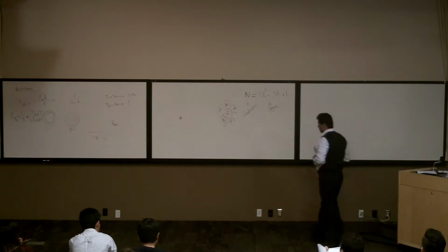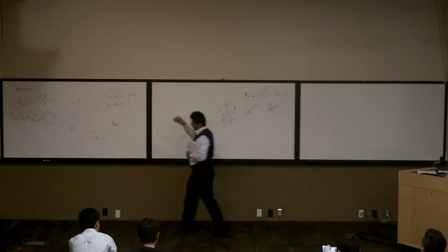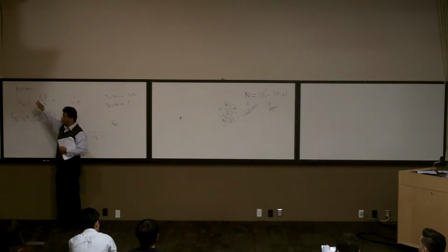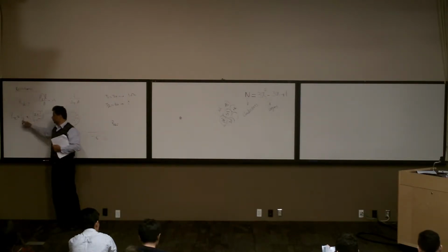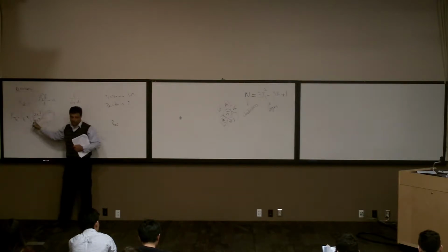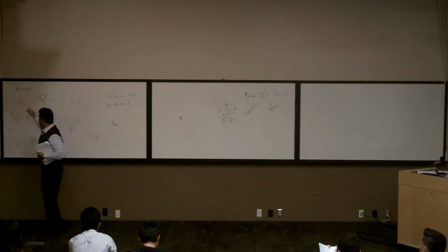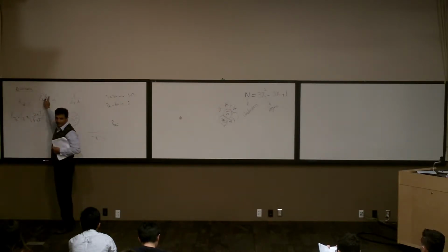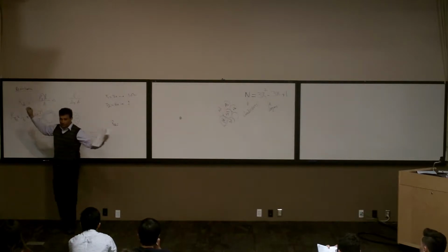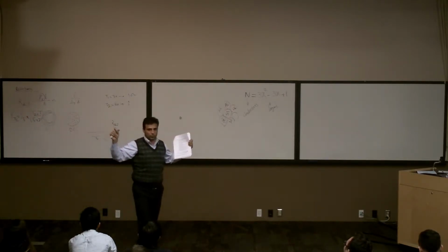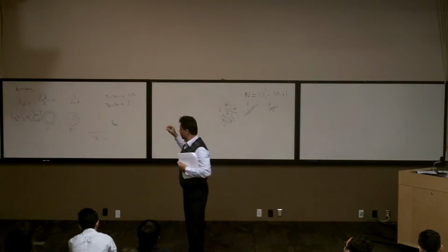But in general, we have a DC resistance, which we can calculate this way. DC resistance could also be a function of temperature, which we can calculate the new value by doing this equation. And the spiral length of the wire can affect this L. When we have an AC resistor, the L is longer than what it is. For example, a 1 meter cable is using 1.1 meter of the conductor.